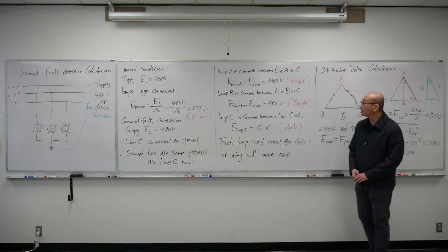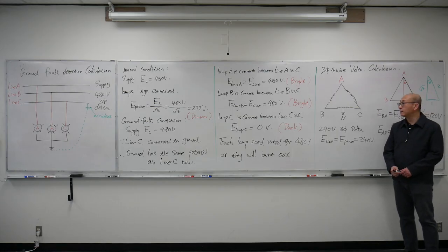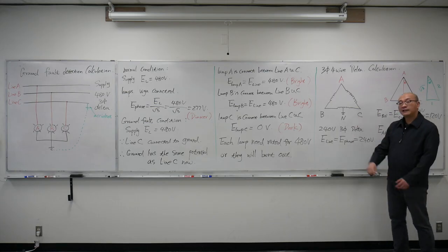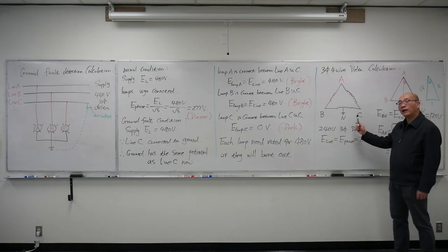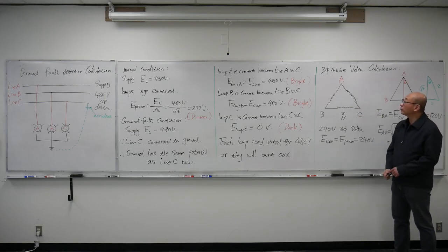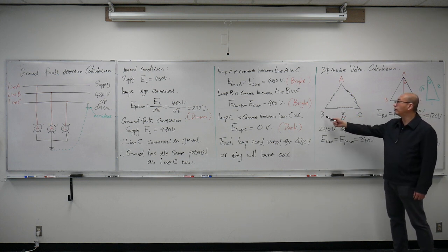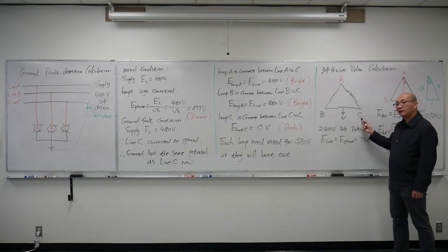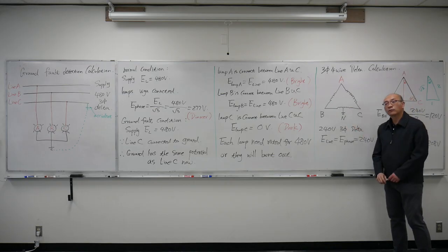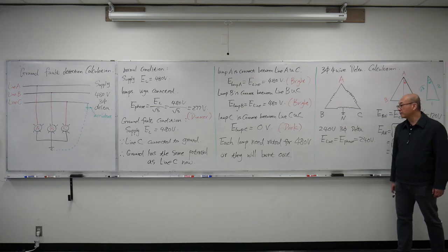Next, we're going to cover the voltage calculation in a three-phase 4-wire delta system. In some industrial places, they want to use 120 volts for the receptacles for certain kinds of lighting. So even if they have a three-phase 3-wire ungrounded delta system, they will ground the center point between phase line B and line C, creating a center point to ground, to put a neutral conductor in there to become a single phase 3-wire supply.